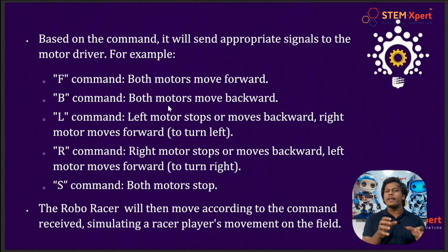And I told you when the S command will be transferred, right? So just keep in mind, this one is really important. Whenever you hold the button, the letter it stands for will be transferred, and whenever you release the button, the command S will be transferred. And if it's received by the board, the robot will stop. So that's all about the concept that we'll be focusing on today.